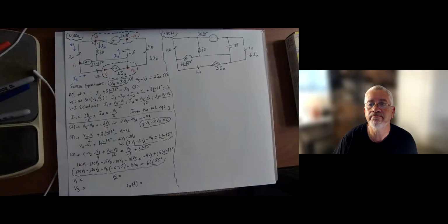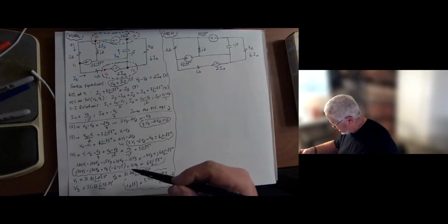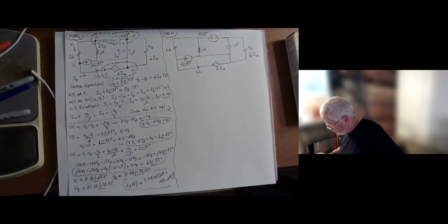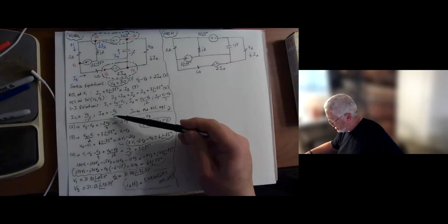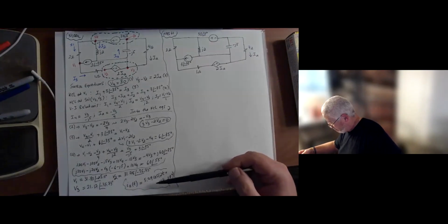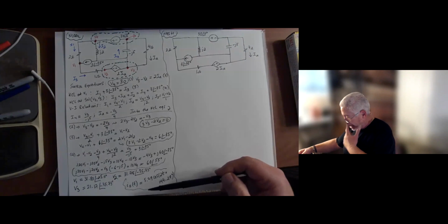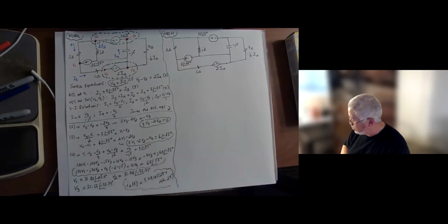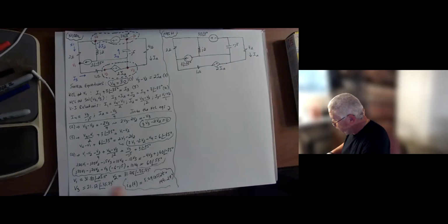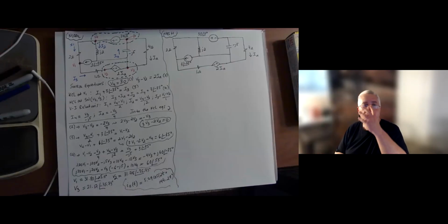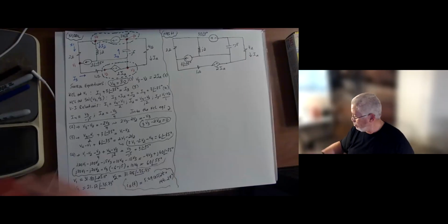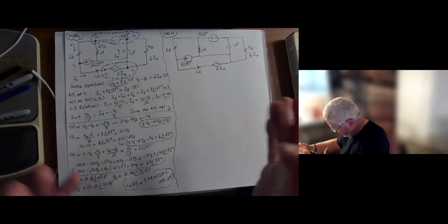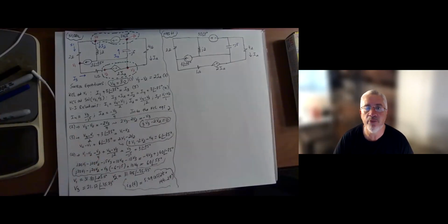Hang on a second. So I went into my calculator and calculated the node voltages, and from the node voltages, particularly V3, I can take V3 divided by minus 4, and I get essentially IA in phasor, and then I get IA in the time domain. That concludes my problem here using nodal analysis. Normally I would write the matrix here, obviously, to show you how it is, but I don't have enough room to do so. I do want the side by side so that you see how this method maps out one versus the other for the same problem here.